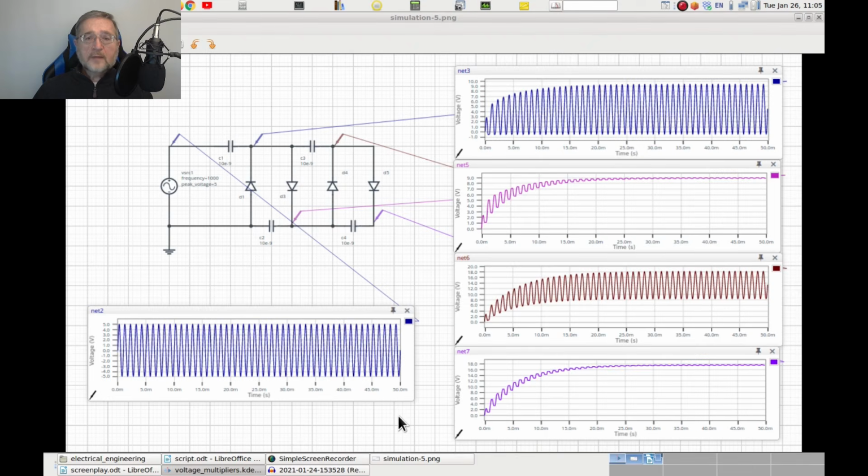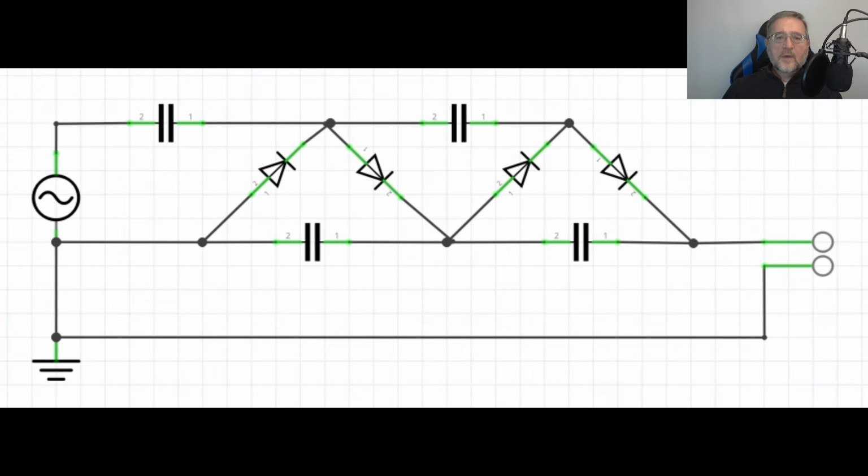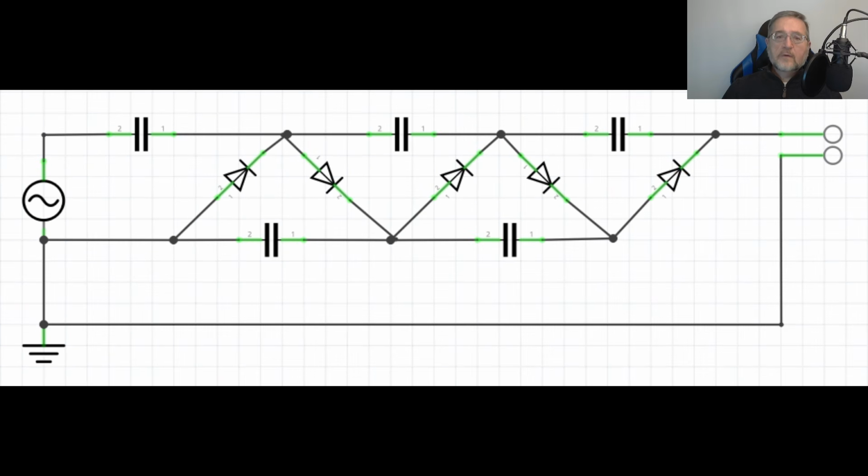And now, if we add one more diode and capacitor, we can rectify again the last signal and obtain an almost constant voltage at the end of this last capacitor, like in this diagram on the bottom right of the picture. Like we did with the DC-DC multiplier, we can draw the circuit in a slightly different way to better recognize the various stages. This is a circuit with one stage, with 2 stages, with 3 stages, 4 stages, and so forth. It is just a bunch of components organized in triangles. The more the triangles, the more the stages.